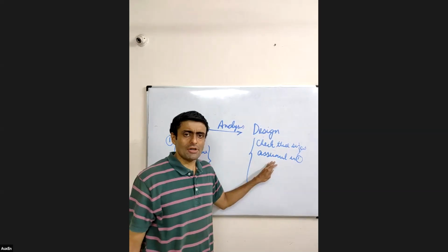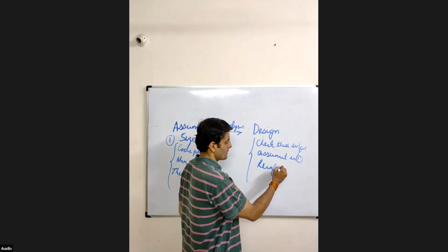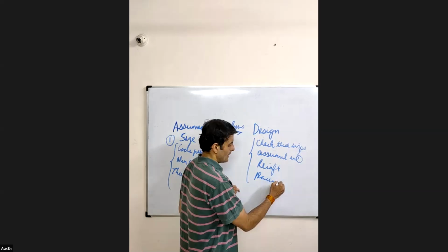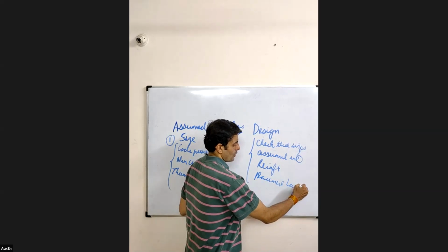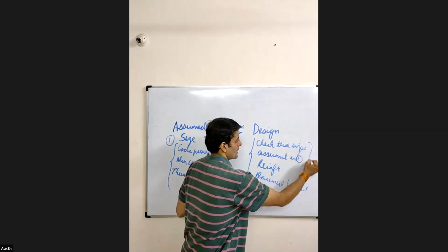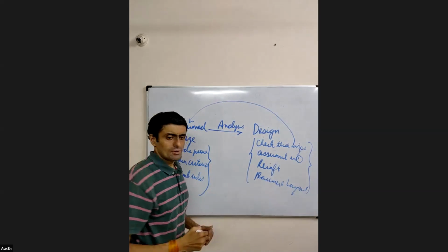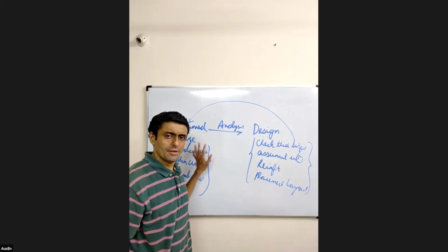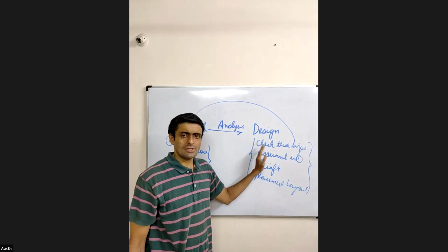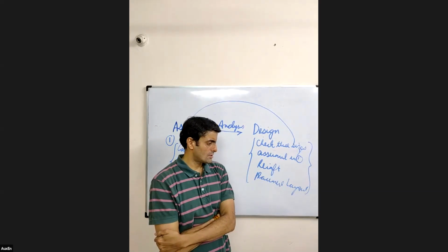If these sizes are found to be okay, you may go for reinforcement calculation, plus you may go for placement and layout, and your process would be complete. Okay. If these sizes that you had assumed in 1 are not found to be sufficient, then you go back to your first step. You again choose some sizes, you again go for the analysis, again go for the design. So therefore this process is called an iterative process.